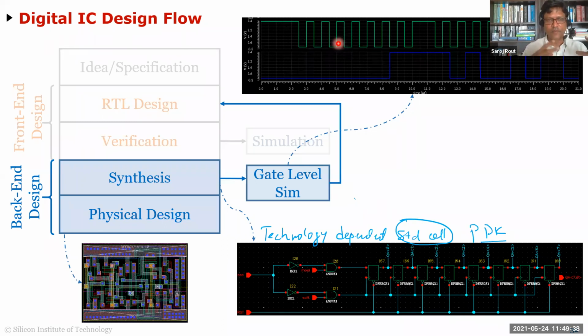If your design is very simple, you can use a very simple synthesizer like YOSYS, like you did on EDA Playground. If you go to EDA Playground, on the left side you'll see synthesis. There's a tool called YOSYS. It's a free tool. You can play around with it, write a small piece of code, and do synthesis. You'll see it'll design it.